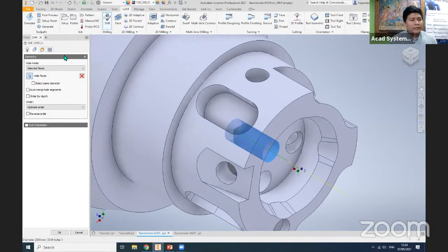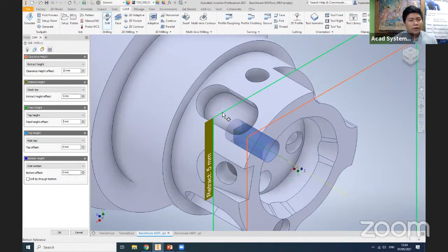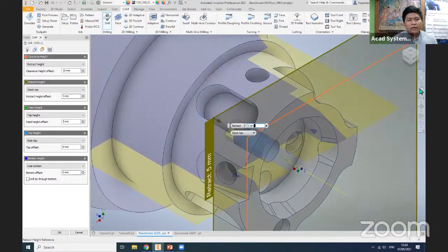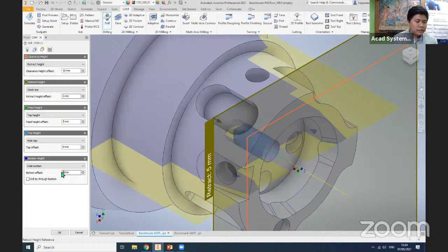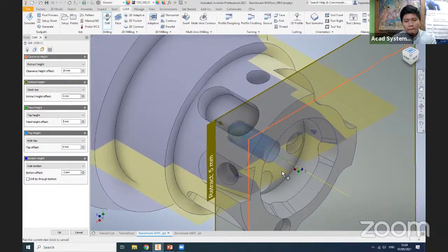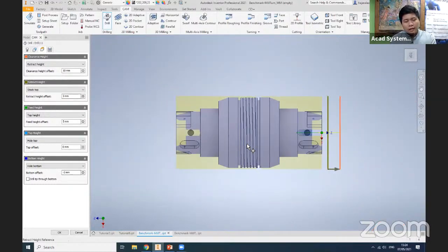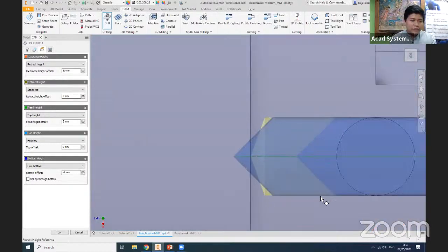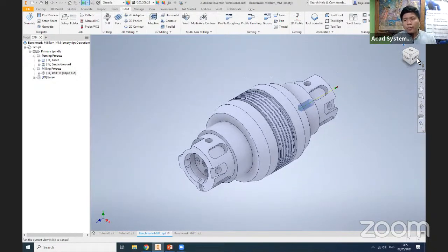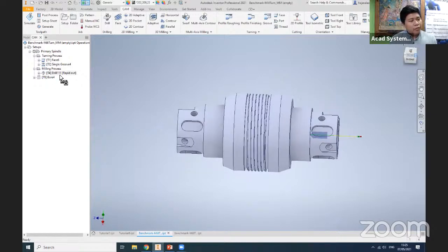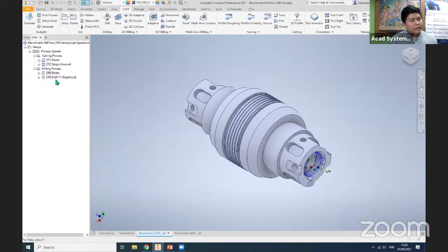Over here you can change the location of your second object, which is here, the retract, and also your bottom hole. You want to put it a little bit deeper, so change on here and add some offset. For this case, I just add 0.2 mm offset. Over here you see a slightly different size, and later you can change your tools directly. So I hit OK first. When I hit OK, what happened? I already created this one, the drill one.